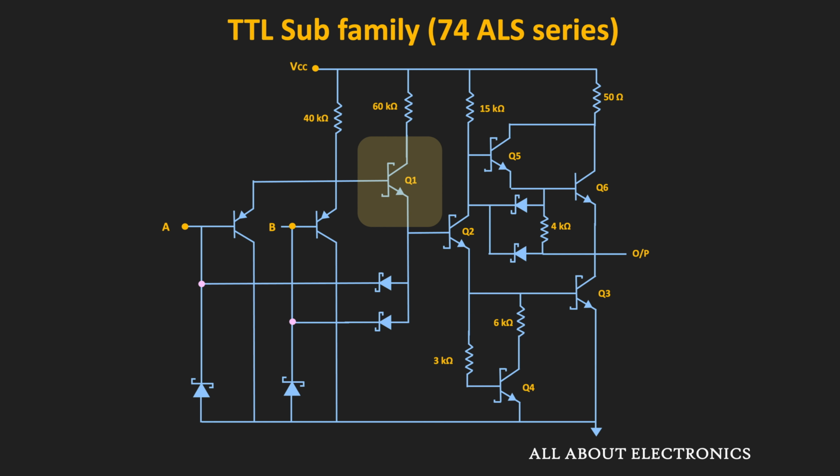So apart from that, if we see the second change, then now on the input side we have the PNP transistors. So first, let us understand why these transistors were introduced. So here, due to this additional Q1 transistor, to turn on this Q2 and the Q3 transistor, we require the additional voltage of 0.6 to 0.7 volt. That is the VBE of the Q1, right? That means due to this additional transistor, the voltage at the base of the Q1 should be at least 3 VBE drop. That is the 1 VBE plus the second VBE and the third VBE. So due to this additional transistor, the required input voltage to turn on this Q2 and Q3 will also increase.